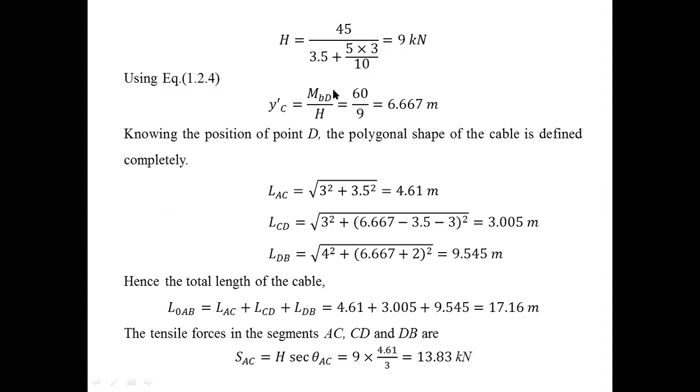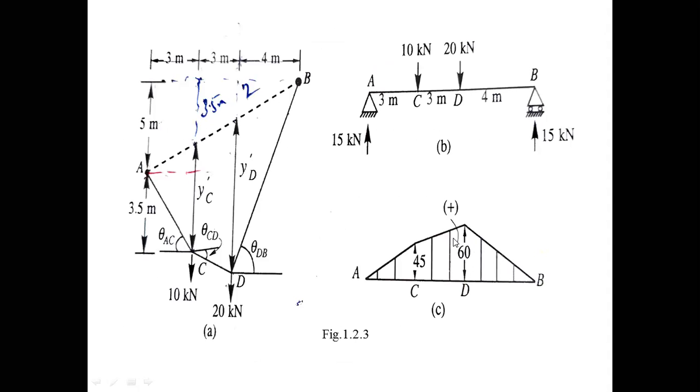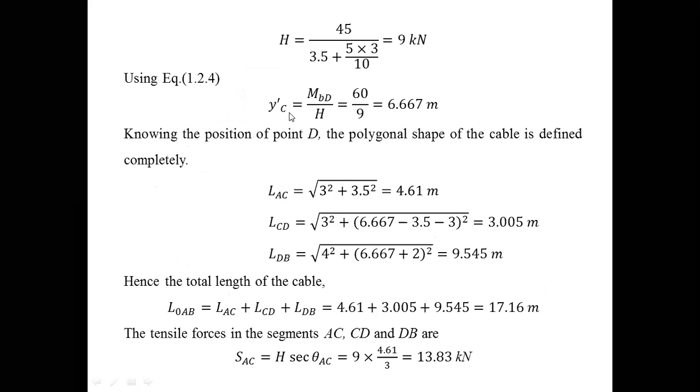And once you know the horizontal component, you know the bending moment at D. How much? 60. And you know H, you know M_B. Then you find the y'_D easily. So y'_D, sorry, here I wrote y'_C, but it is not correct. I will rectify that one.